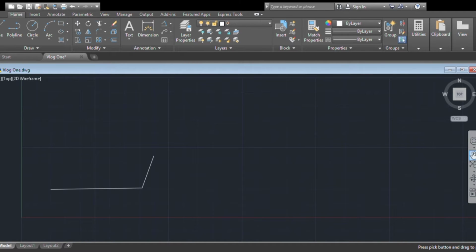Let's have the line directly to the end point, and let us enable the ortho mode for us to have the guide, and simply click it. So since we are on the ortho mode, we just have to enter the length, which is 2.3. Drag your mouse horizontally and just enter.